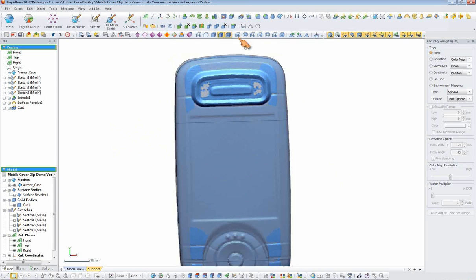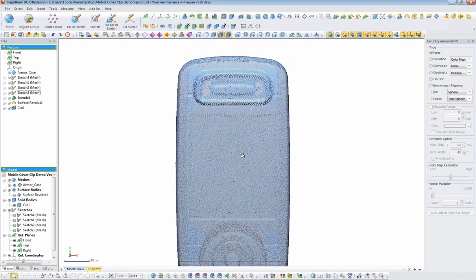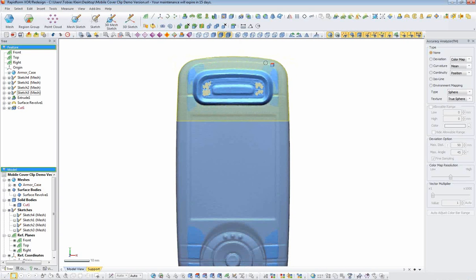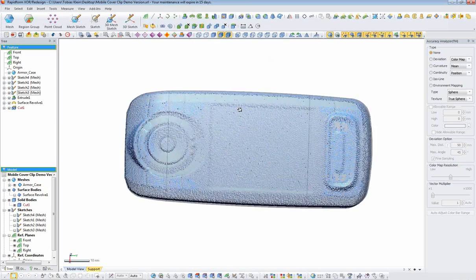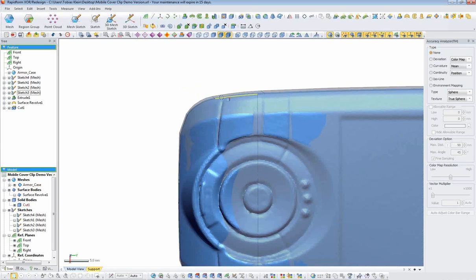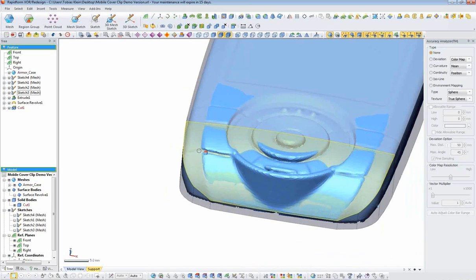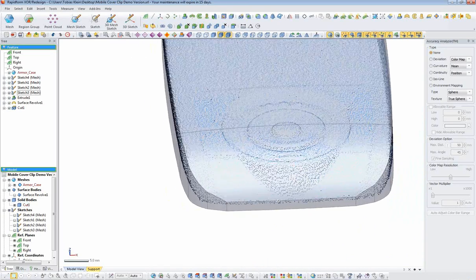Basically, when you look at it, we have some transparency here. We can turn on transparency of the object. So when you look at the top, you can see that this top line, this character line, is a little bit offset from that top line here, and this is also a little bit offset. So you can use those features and offset them. And on the other side, if you look at this character line, it is flowing down to that point, so we can also use an offset from here and connect it with a tangent line to here. So we get a really nice curved character line down to here.